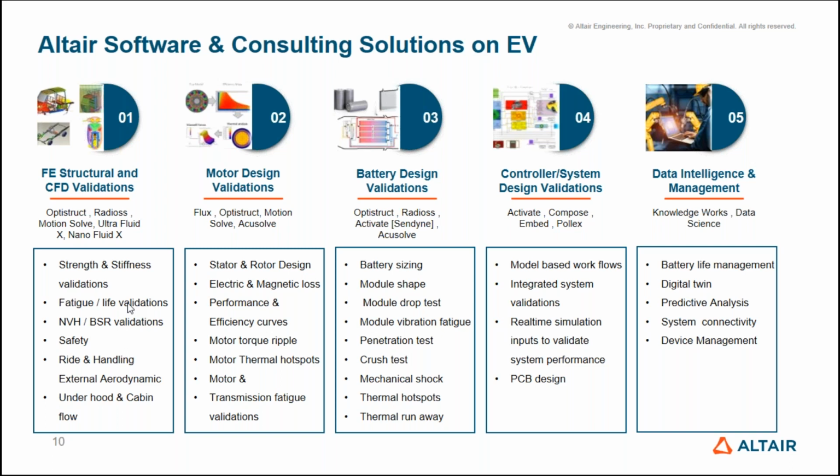The next one is the battery design and validation. For that we have AcuSolve, where you can do the battery thermal management. Say, for example, you have a battery pack, and in that you have battery cells. You want to see the temperature distribution on the battery cells, because the delta T, the temperature difference, is very important while designing any battery pack. It should not go beyond 5 degrees Celsius. So you are able to identify and modify your design by doing battery thermal management simulations.